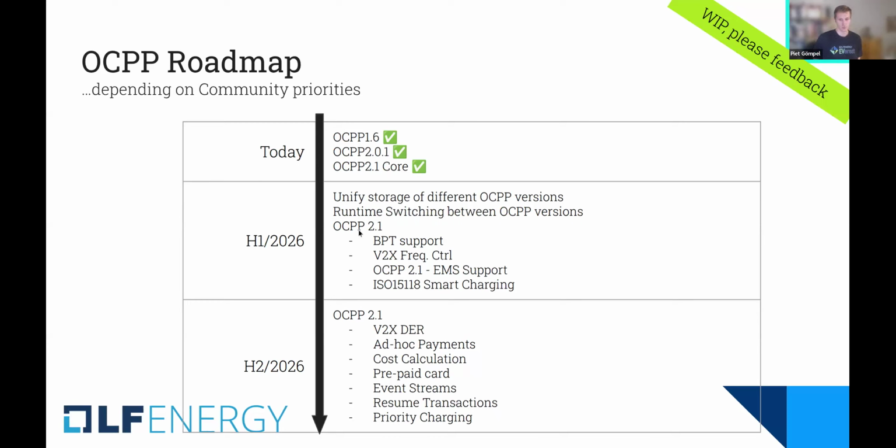And then we'll, of course, focus on the implementation of OCPP 2.1 of the new additional functional blocks like BPT support, frequency control, EMS support, and also ISO 15118 smart charging. And in the second half of 2026, we will continue with the remaining functional blocks of the specification.